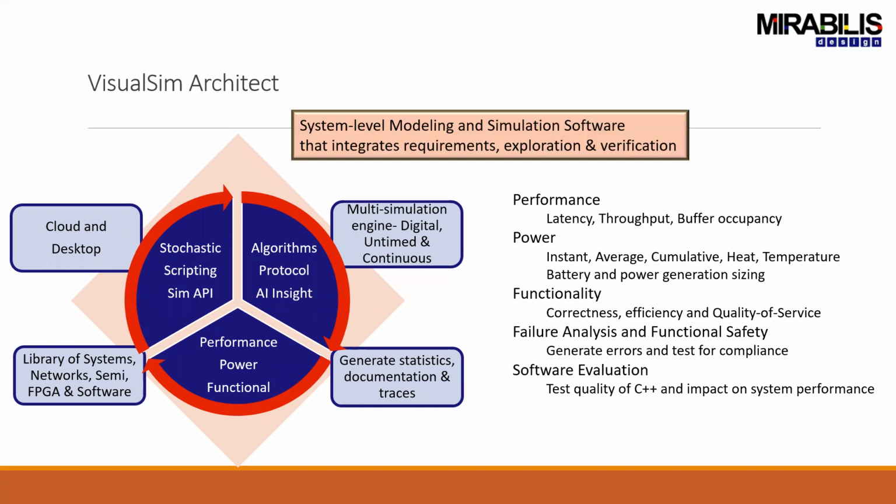So for example, even with the die, I can reduce the number of links, or lanes. Or I could do it in such a way that the flit size becomes smaller midway through the design. Or I can have spurious addresses being sent across the die-to-die link to see what happens to the overhead in the system as a result of doing something like that. So a variety of failures can be generated.